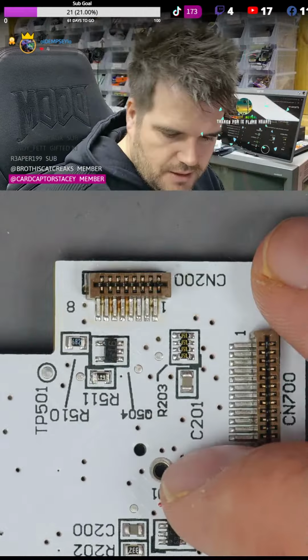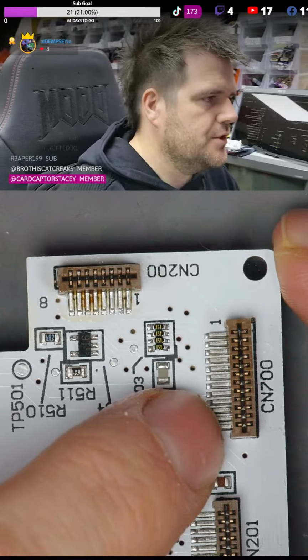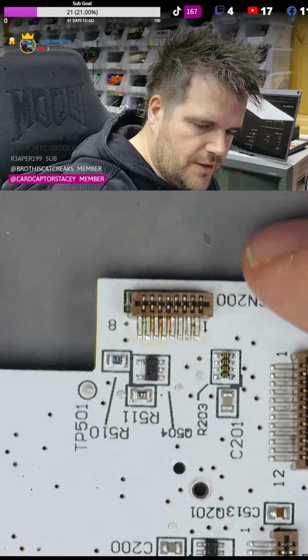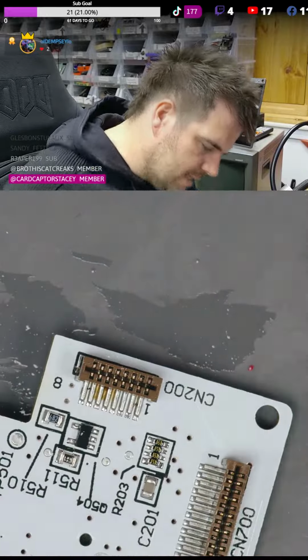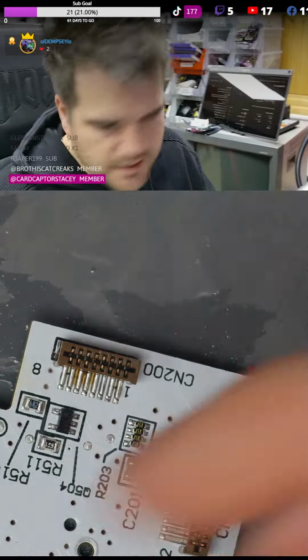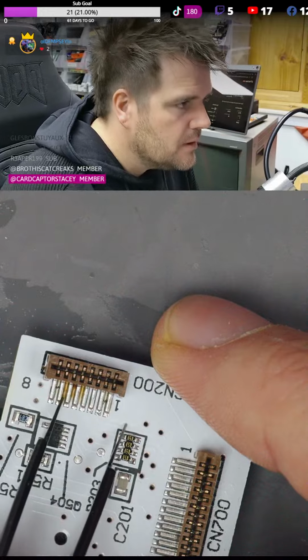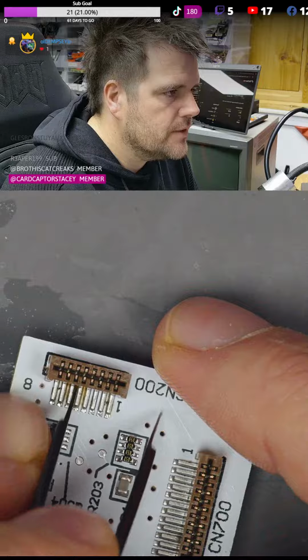But you see how much more work that was to do than hot airing. So you can see that's why I prefer hot air, because the other ones we just pretend all the pads were hot aired and they're all perfect. Whereas the hand soldering like that, you can see, takes more time and takes a lot more work to get anything that you'd say is as good as the hot air one. Plus the flux does not want to come out of the middle of these. Let's give it all a helping hand.